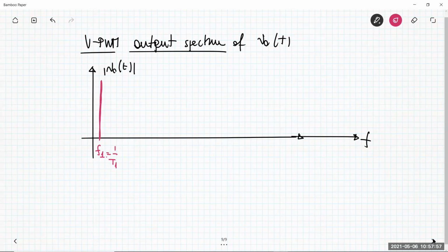Then I'm drawing now the typical waveform that you can have, generally speaking; then we can cancel out some harmonics. You can have something at the switching frequency, something at twice the switching frequency, harmonics at three times the switching frequency, etc. So you have all the components around the switching frequency.